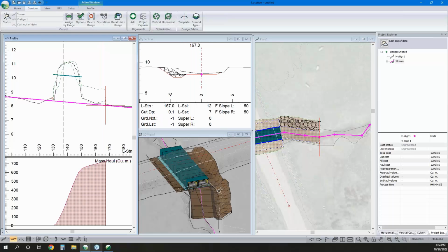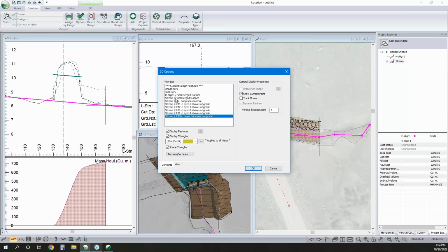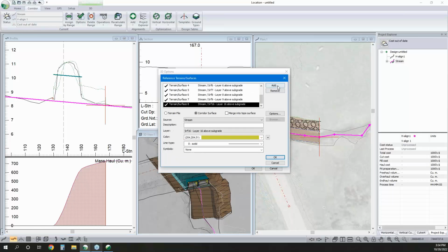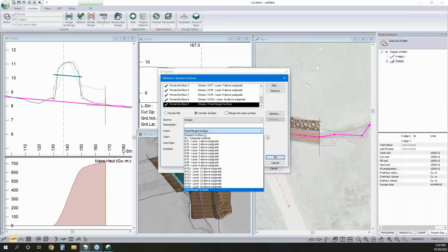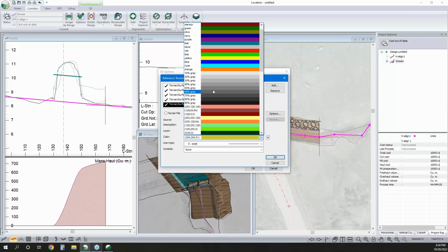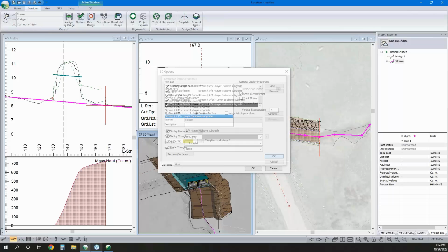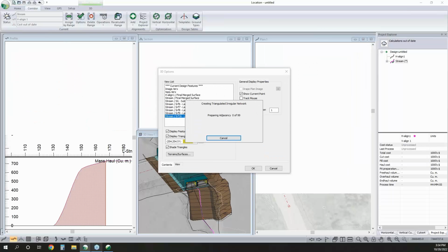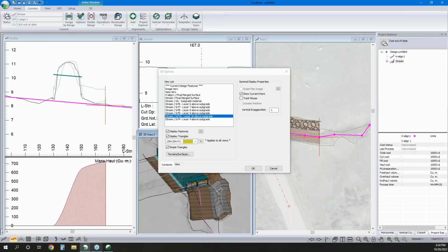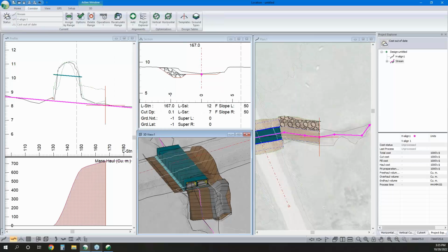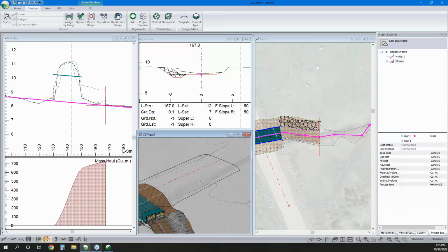If I want to see that in here, once again, if it's a unique layer and I don't want to just show the final merge surface, I'm going to have to show it here. So that's in there as layer 4, and we will make that 40% gray. So we've even armored our outlet as we round the bend there. So that is how I'd figure out my culvert alignment, and I've modeled it. I'm happy with the length, at least at a glance.